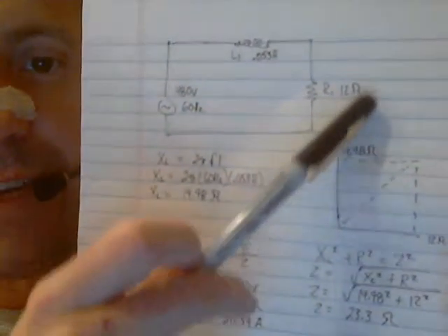Now that we know the current flow in the circuit, we can also find out how much power is used. And remember, there's going to be two values here. There's an apparent power, which is going to be the total when I multiply the voltage by the current. But that's not really true power, because remember, the power that is as far as the coil is concerned is not used. It's stored in the form of a magnetic field. Now the power that is generated by the resistor is dissipated in the form of heat, so that would be true power, which could be measured in watts.